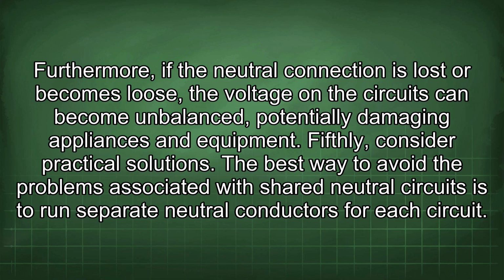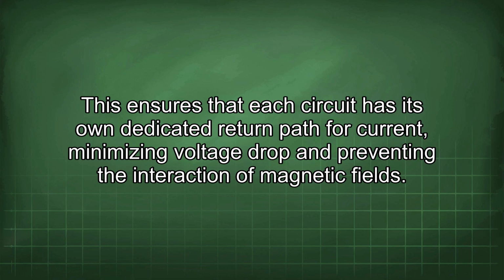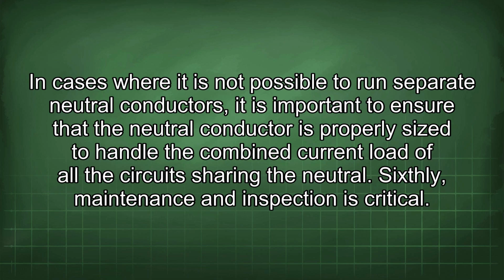Fifthly, consider practical solutions. The best way to avoid the problems associated with shared neutral circuits is to run separate neutral conductors for each circuit. This ensures that each circuit has its own dedicated return path for current, minimizing voltage drop and preventing the interaction of magnetic fields. In cases where it is not possible to run separate neutral conductors, it is important to ensure that the neutral conductor is properly sized to handle the combined current load of all the circuits sharing the neutral.